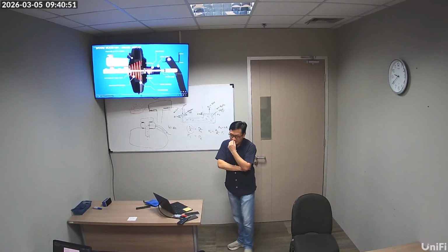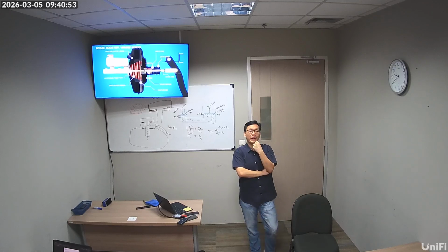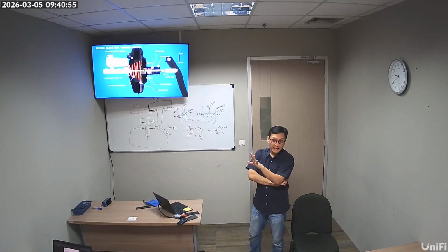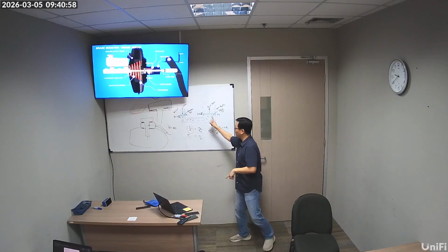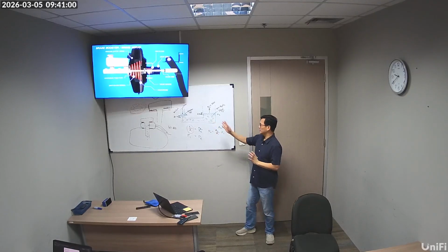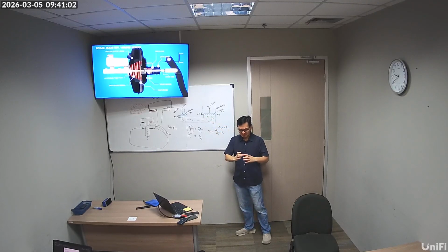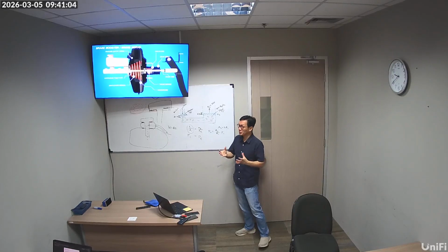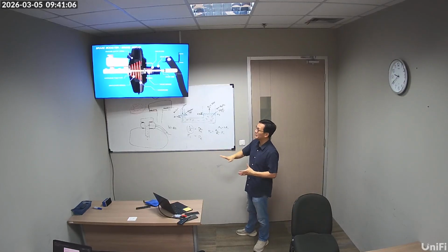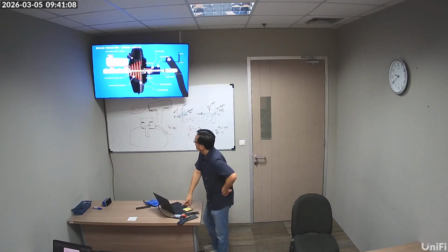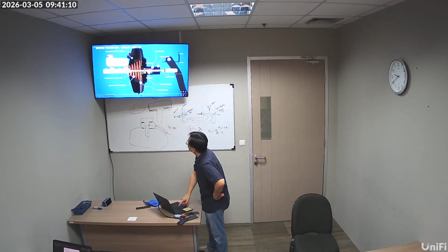Okay. So this brake booster is something to help you push, because even with the hydraulic system, think about it, you're only getting what, 5 times multiplication? So this is still very hard. Where does the power to help you come from? It comes from vacuum.